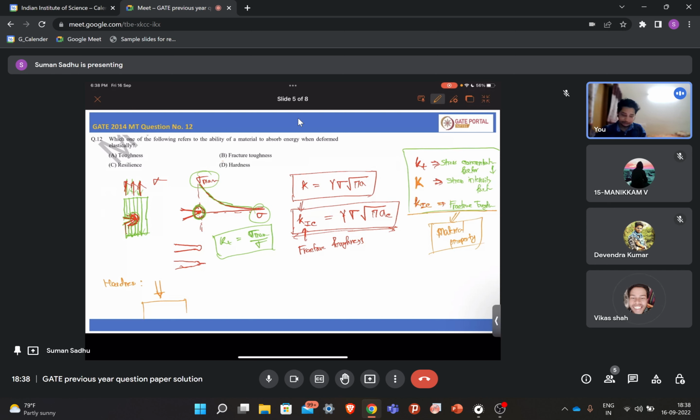So in case of Vickers it is a diamond shape, in case of Brinell it is a ball shape, right? Yeah. So basically you are making an indentation here, right? In case of Brinell it will be a round, semicircular kind of shape. So you are deforming your material or your sample locally.